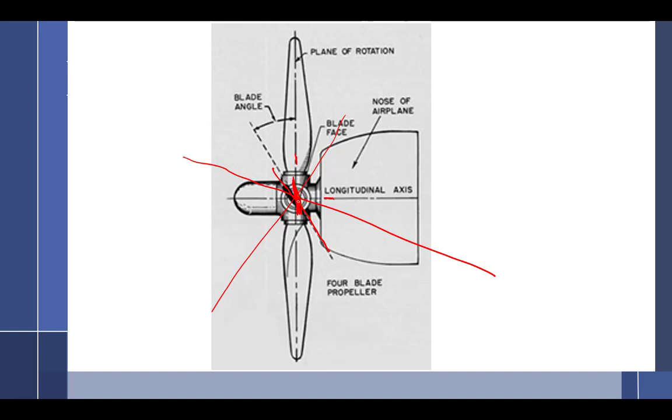So what was P factor in an airplane? The descending blade has a smaller angle of attack than the ascending blade, which has a bigger angle of attack. So you have dissymmetry of attack on your blades, and it's going to cause a plane to go right or left. Left, because I put right input, so it's going to go left. You have on the right side, it's pulling more, so making the plane go left. Where you started out straight and level, the right blade and the left blade, or the descending and the advancing blade, had equal angle of attack. And then the aircraft tilts forward, and that made the blades change, so one went flat and one took a big bite, right?